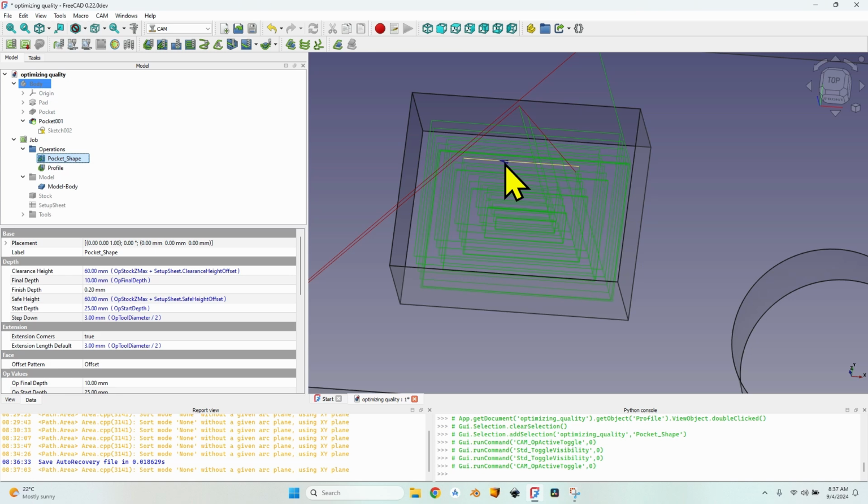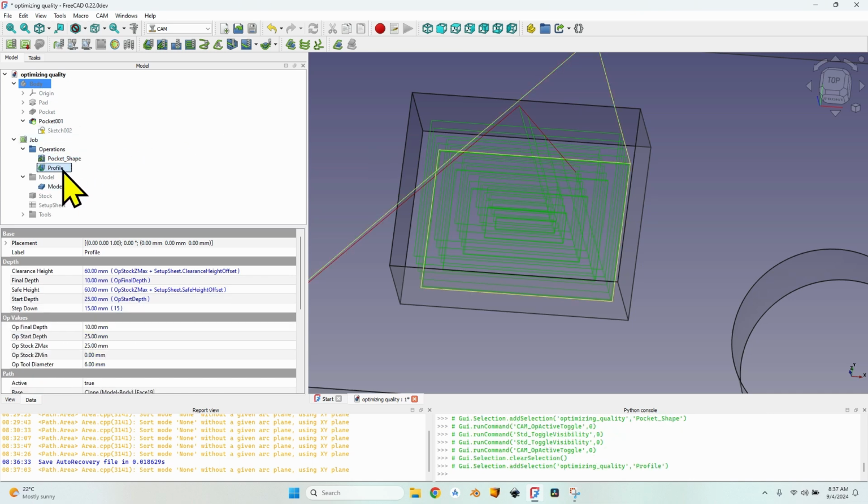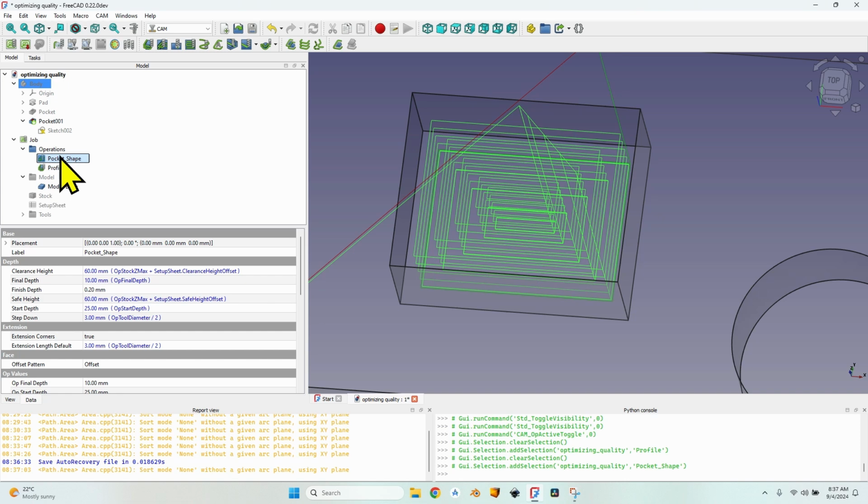One thing to take into account is that when milling this profile operation at the end, you might get some lines on the outline. Depending on the machine, the cutter head might not be exactly in the same position as it was when making the pocket shape finish, and in this situation, if the profile will leave some lines on the outline, you can do another little trick.